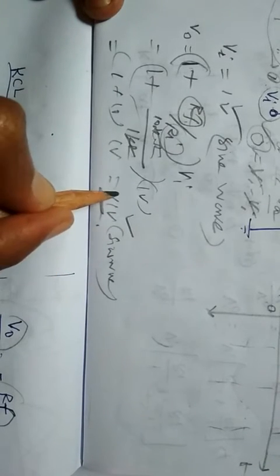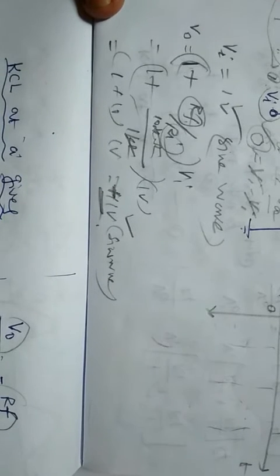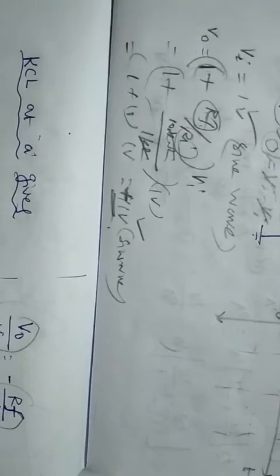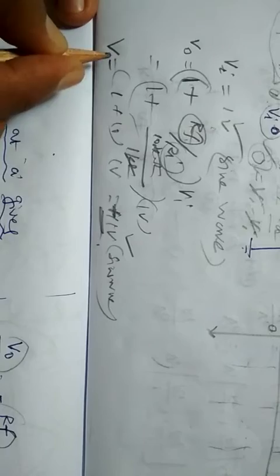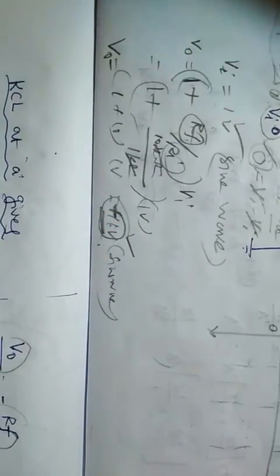And the main important thing is that it is plus; the potential's nature is positive. So you have to draw the waveform for a 1 volt sine wave input and an 11 volt sine wave output. V out equals 11 times the amplified version of the input.